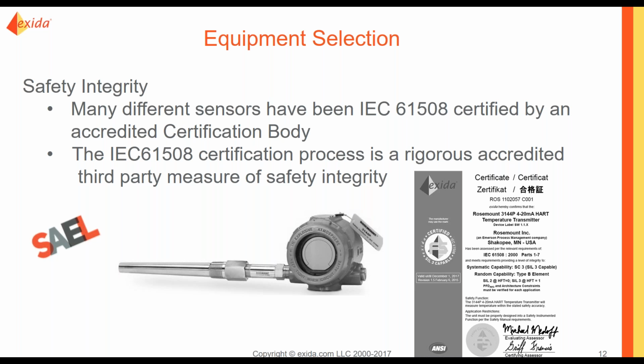If you want a list of current and valid IEC 61508 certified devices, they're maintained at a website called the SAEL, the Safety Automation Element List. And you can find that at www.sael-online.com.